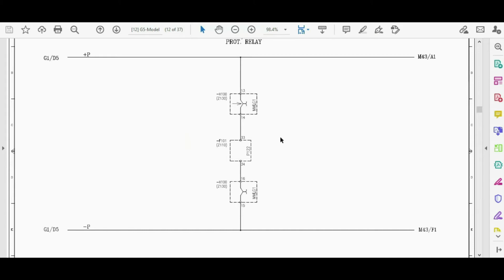And some other designers believe that they don't need to use a test block in the path of the DC power supply of the protection relay. And the reason is, before going to the test of the relay, all the time the circuit breaker is open and everything is okay for the testing of the relay. But if the panel is energized, the commissioner must know that he must open the trip wire from the trip circuit, and then he can insert the test handle into the test block.